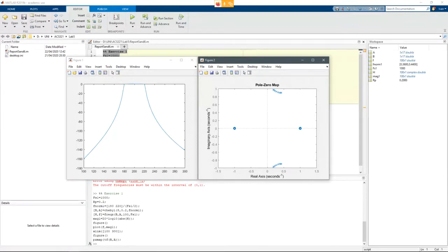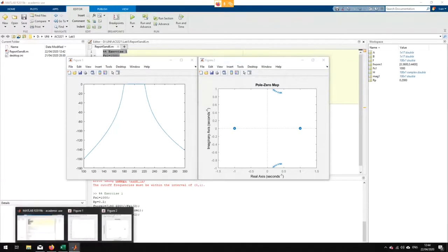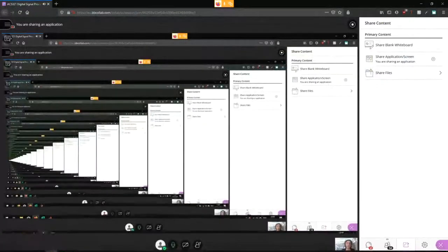So here in the Z-plane, on the unit circle, we start from omega equals 0. Now omega is 0, so we have a zero, so the frequency response is 0. When we move forward in the Z-plane, we get far from the zero and close to the poles, so our frequency response increases. And when we get far from the poles and close to zeros, again we have a decrease in frequency response.